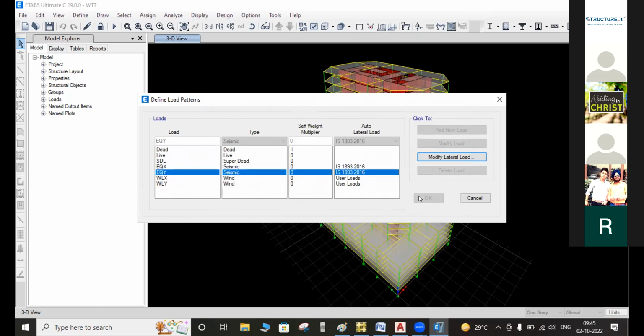When the earthquake strikes, the unbalanced vertical force will be generated. We require the base shear, which will be equal to and balance the unbalanced forces. Otherwise, our structure will collapse. So we have to put the parameters in these templates. When we analyze our models, we get the base shear values. When we create the report, it also gives the base shear.